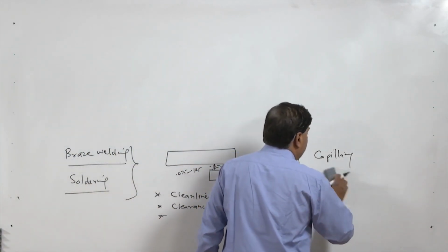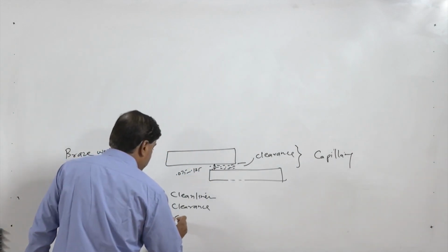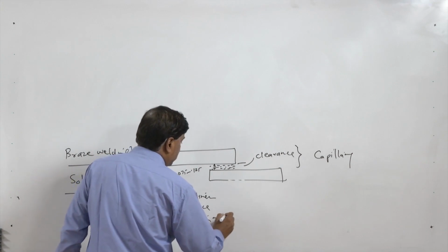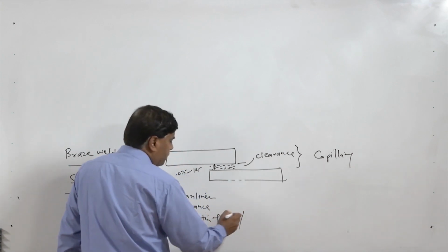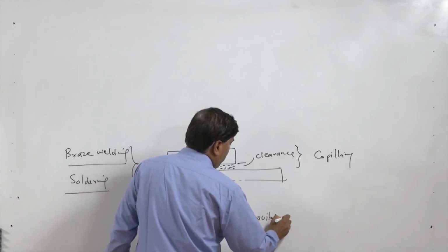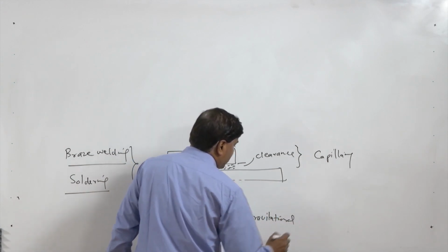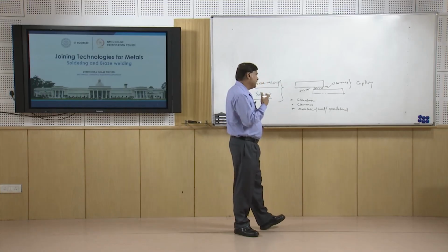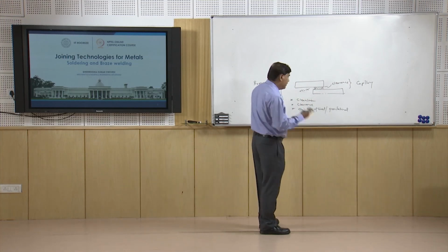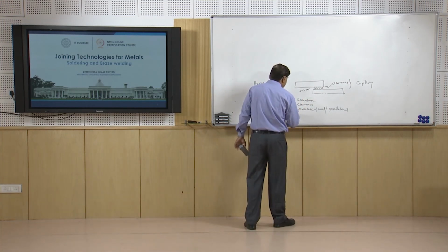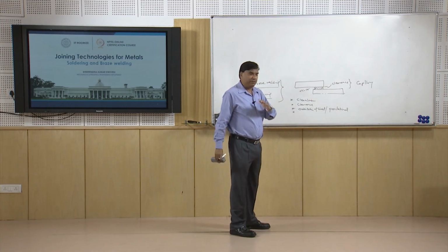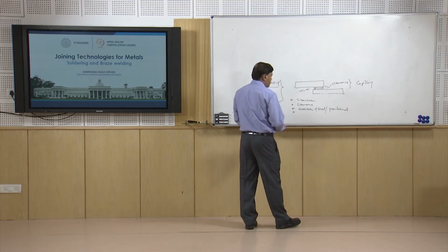So, indirectly we can say the orientation of the plates or sheets matters, and this effect is primarily due to the gravitational force. How gravity assists or resists the spreading or distribution of the solder will determine the uniformity and ease of spreading of the solder.